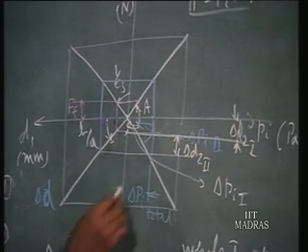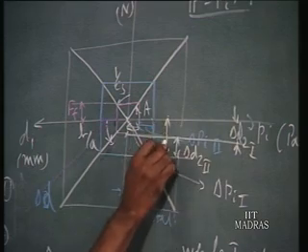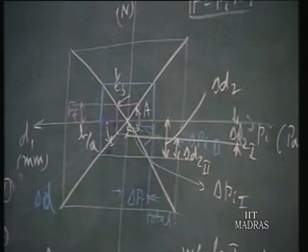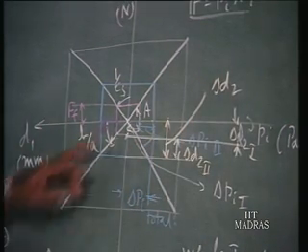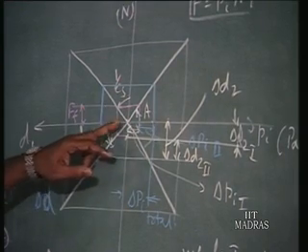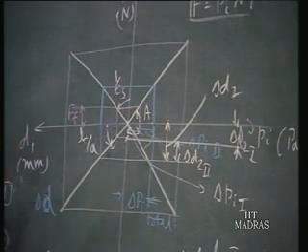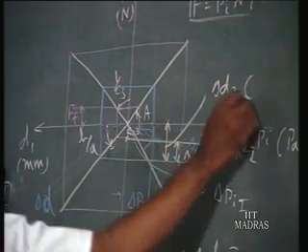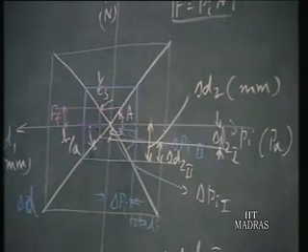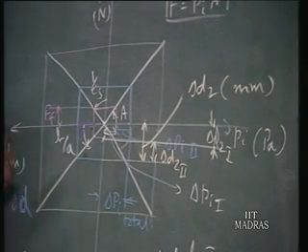Both put together will be delta D2, the total error in millimeters from both error sources, one friction and the other play. So much millimeter will be the equivalent error in output reading for these two sources.